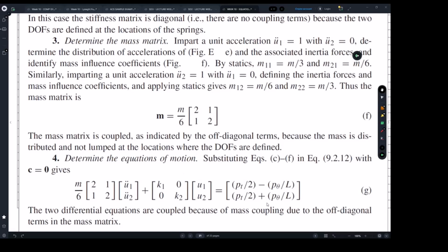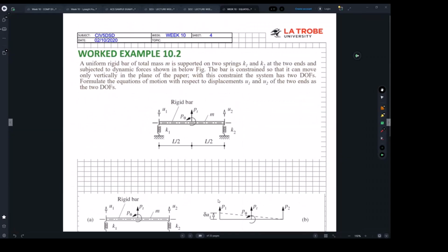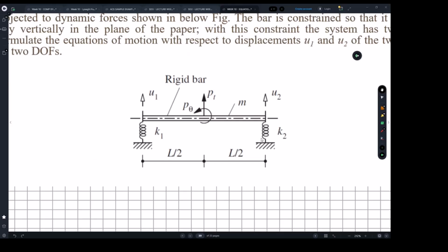We wanted to develop an equation of motion. Next week, we can do more steps to find the time period and the frequency, which is the key thing we need. Now, this is a very, very practical application, as I said, because when people look at this, they will think it's a 1 degree of freedom system. No, it's not, because we have 2 frames of springs that will make it double degree or 2 degree of freedom. And there's a lot of applications.